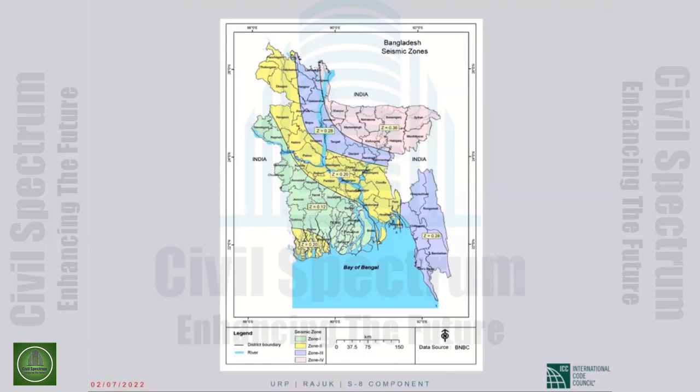So the brick, not only in Bangladesh, pretty much everywhere that brick infill is used, the infill is not reinforced. So initially, the infill contributes to stiffness, and the building has very high stiffness because of the infill. But then in an earthquake, the infill is among the first to fail. It cracks diagonally, and then it can just fly, even killing people.